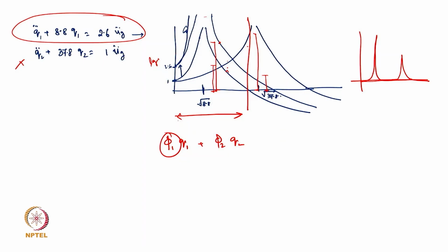So now if you see higher modes, your frequencies will be higher. What we talked about is the first mode's frequency. There will be second mode, third mode, fourth mode, so frequency will be higher, because we take the highest time period and then the second highest time period, like this. But when we talk in terms of frequency, we take the lowest frequency, then second lowest, third lowest, in ascending order. In case of time period, it is descending order.